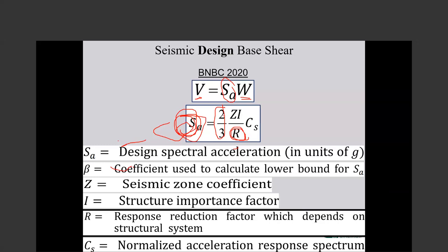When we say we accept damage, it's because this load, usually for buildings in earthquake-prone regions, is much more than other loads due to the wind, due to the snow, due to the live and dead load. So we divide it by a number, by R. So here we accept damage. Here we impose damage.